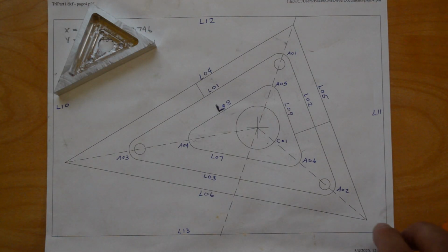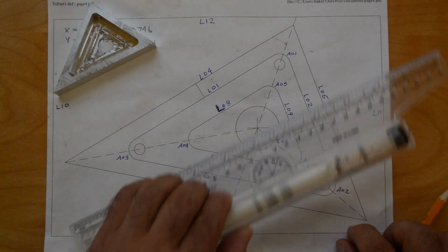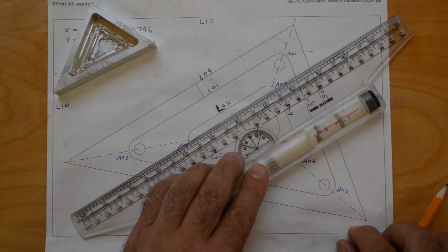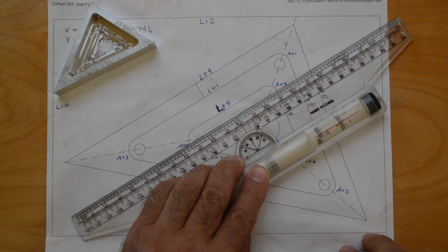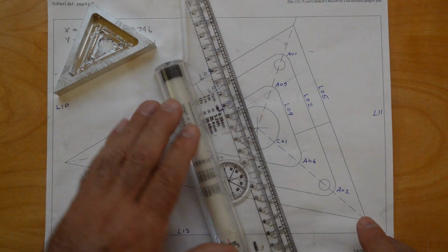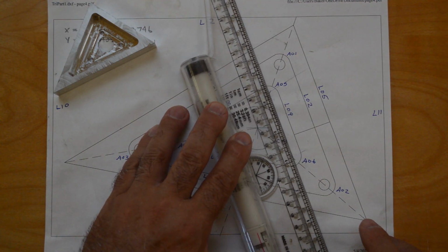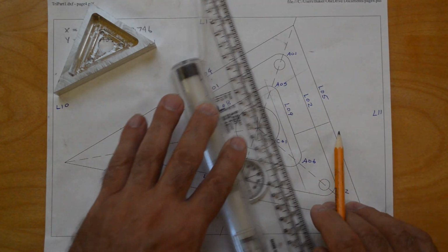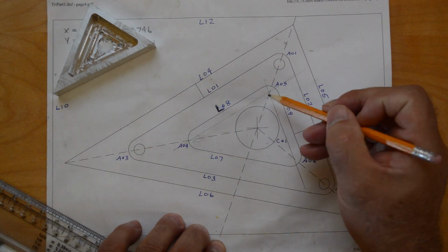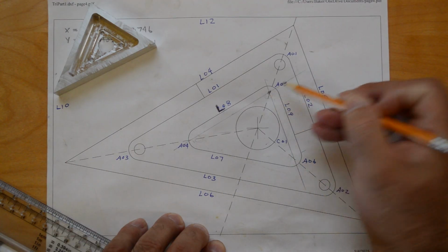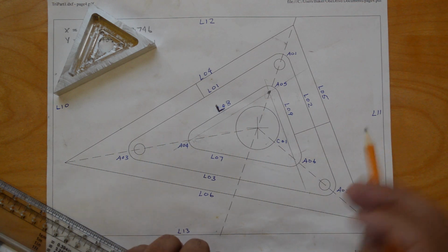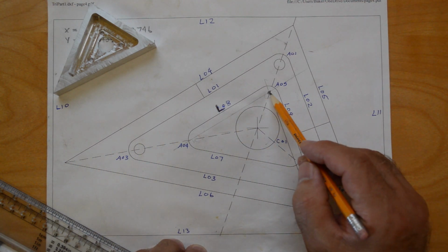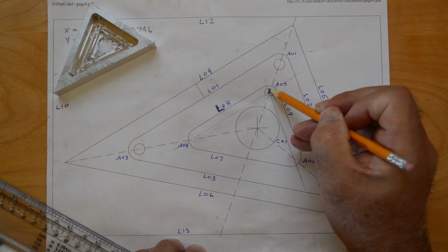If I could simply place a line there, for instance, a line parallel to line 8 but offset by 0.125, and then a line parallel to, say, line 9 and offset by 0.125, then I would have an intersection point here. And that's where the hole belongs, right? At the intersection of these two lines. And so I can do that. I can define these lines, define the intersection of these two lines and make that point. I can even put a circle there if I like, okay?